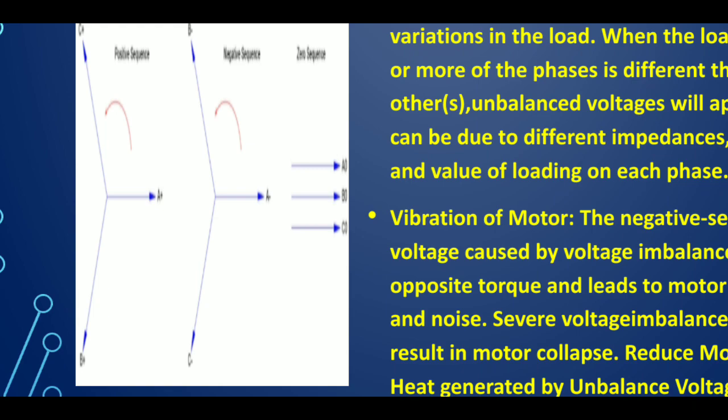That means the direction of the negative sequence is always opposite to the positive phase sequence. We know the forward direction of a motor is always anti-clockwise, so we can write that the positive sequence is anti-clockwise. But if we consider that the positive sequence is clockwise, then the negative sequence is actually anti-clockwise. And if we consider the positive sequence is anti-clockwise, then the negative sequence is clockwise.